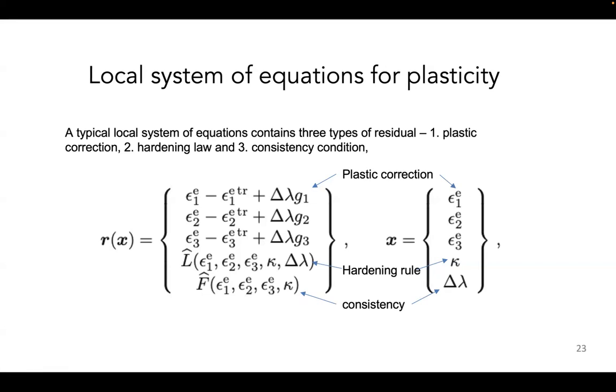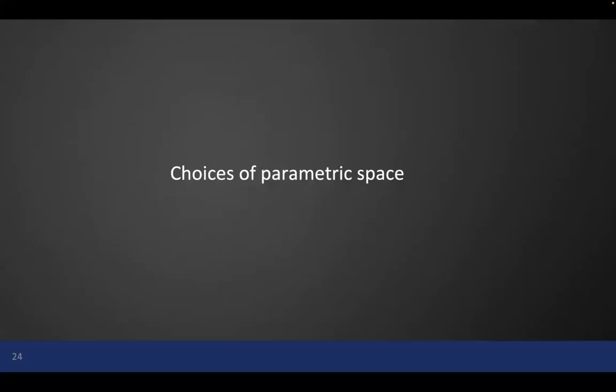Okay, if the material is yielding, your stress is on F equals 0, not F smaller than 0, not F bigger than 0. So you're enforcing that, then it will magically come back with the new stress update that gives you the output. Okay, so this is the classical ingredient.